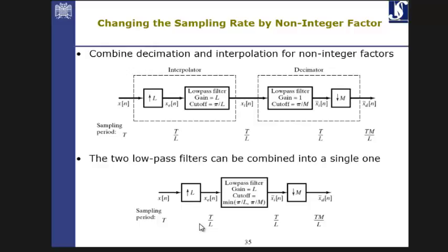So using this structure, you can change the sampling frequency of any signal to any range that you like. Of course, if you want to, for example, reconstruct a signal which has already been sampled at 8 kilohertz to something more than 8, then you will lose some resolution because the original signal is not more than 8 kilohertz. So it's not magic that you will suddenly get more information. But you will have a sense of interpolating the signal.